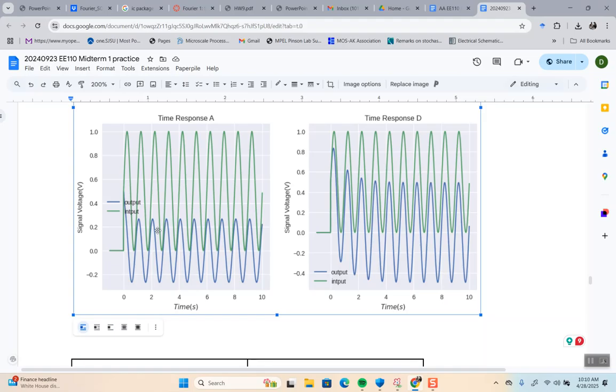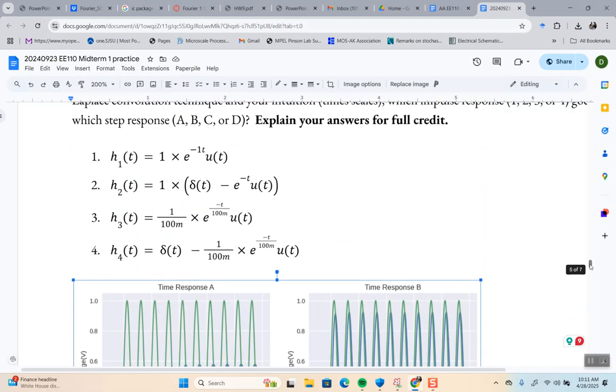And then here, right, it's attenuating. So the cutoff frequency for this is higher than the cutoff frequency for that. And so that means the time constant for this has to be smaller than the time constant for that. And without anything, you can then just go for it.